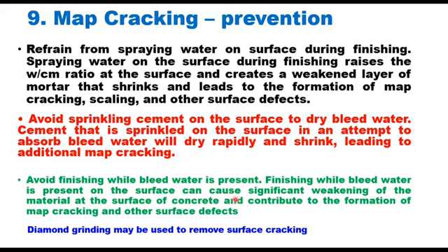Finishing while bleed water is present on the surface can cause significant weakening of the material at the surface, and that can contribute to the formation of map cracking and other surface defects. Diamond grinding can be used to remove surface cracking. That is the only treatment which is possible for map cracking.